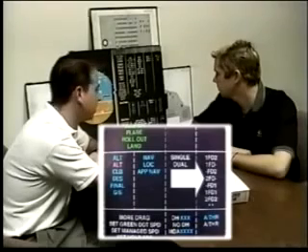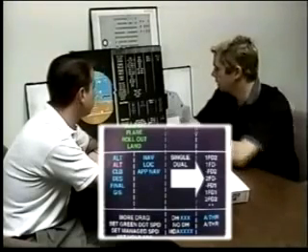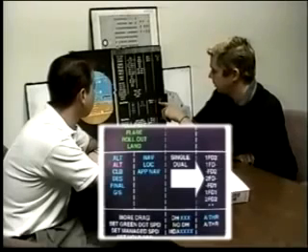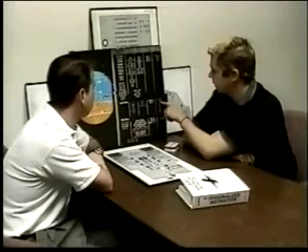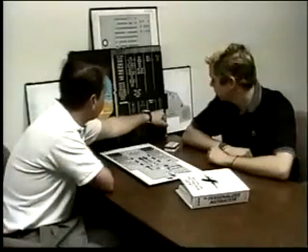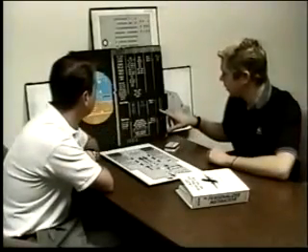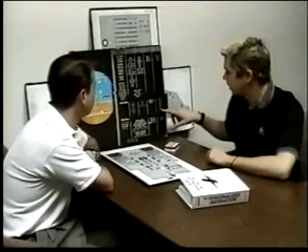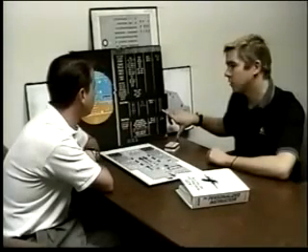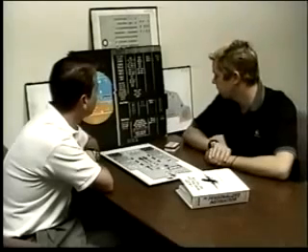What about 1 FD dash? 1 FD dash indicates that, again, the captain's flight director is on as being commanded by flight director 1, but the first officer's flight director has not been selected on. 1 FD1? The captain is on, and number 1's commanding his system. The first officer's is on. Number 2 system is inoperative, so he's going off of flight director 1.